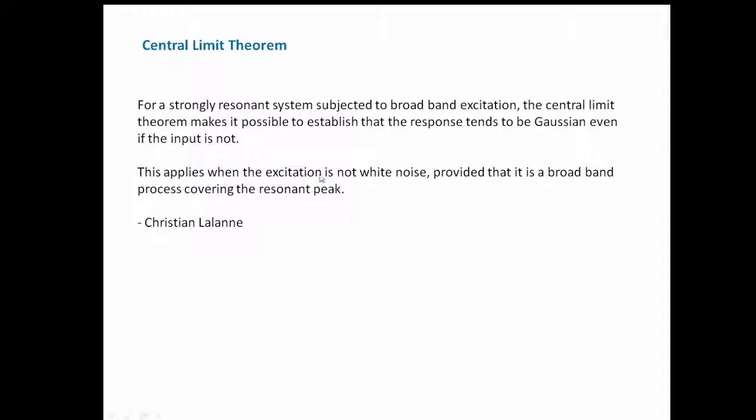This applies when the excitation is not white noise, provided that it is a broadband process covering the resonant peak. So our kurtosis equal to 5 signal was broadband. The energy went up to 2,000 hertz. Of course, there was a little bit of roll-off due to the filtering. But our 600 hertz was well within that frequency band for the kurtosis equal to 5 signal.